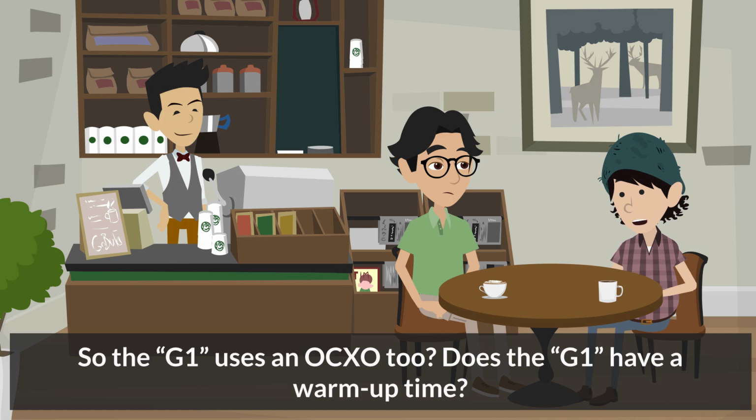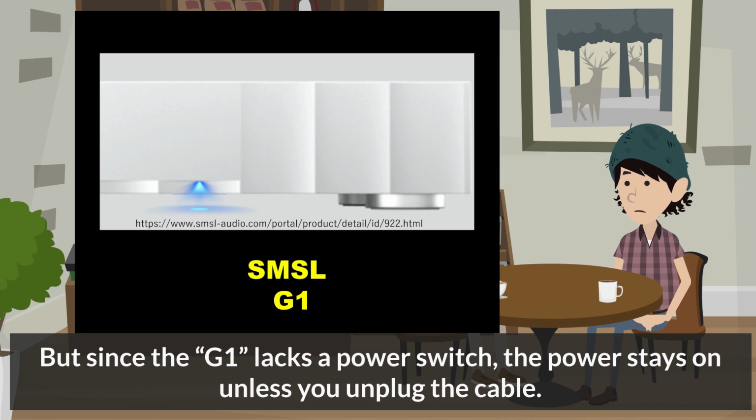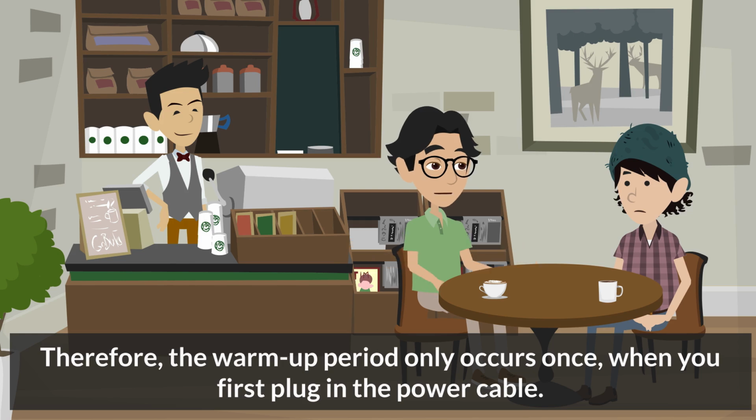So the G1 uses an OCXO too? Does the G1 have a warm-up time? Only when using AC power does the LED flash for about the first 2 minutes until the OCXO's temperature stabilizes, making it unusable during that time. But since the G1 lacks a power switch, the power stays on unless you unplug the cable. Therefore, the warm-up period only occurs once, when you first plug in the power cable.